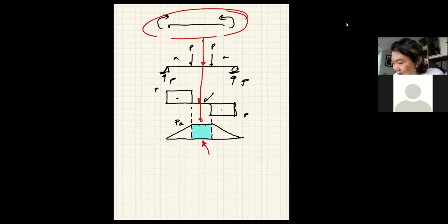But it's small enough. Let's say if you include the self weight into this, what would your shear force diagram look like? It's going to look like this, right? With a slight change in the shear. So if that slope is small enough, we say we neglect it and say this is as close to the pure moment as we get.